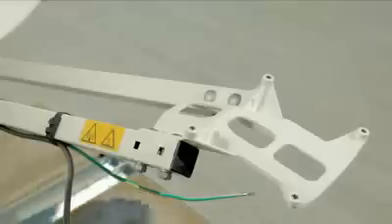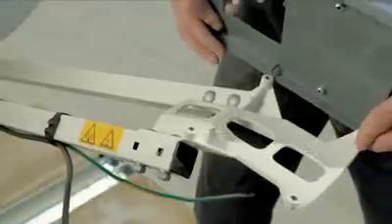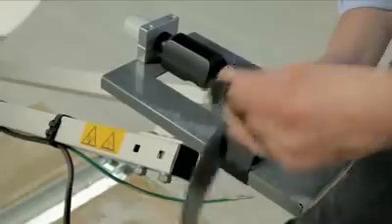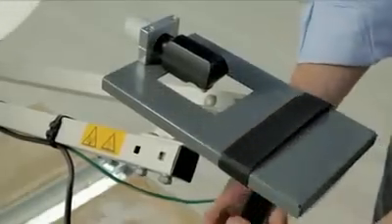Normally, the installation would be on a wall, but to facilitate the filming, we've installed the system on the ground. We will now locate the satellite with the first pointing procedure. Install the KU pointing tool with easy-to-use Velcro, then connect to the analyzer.